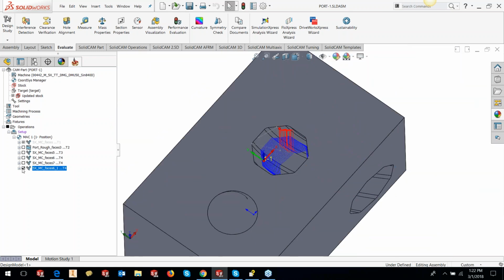Now, you could have encountered such issues many times where the actual surface geometry produces really bad results, and you somehow have to cut the geometry. So today we are going to use a trick. It's actually not a bad trick, but it's a legitimate trick inside SolidCAM. And here we use the gouge check to actually give us a much better result.